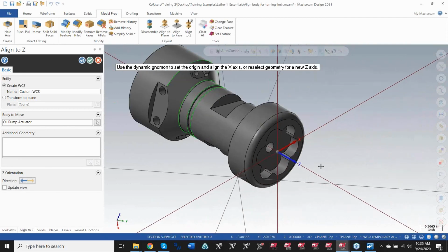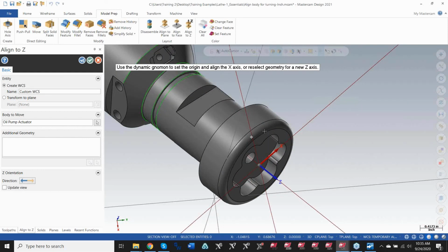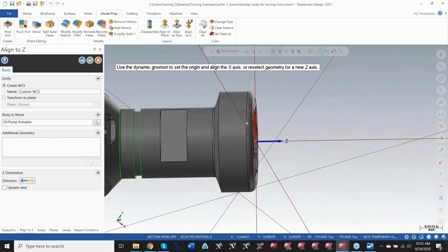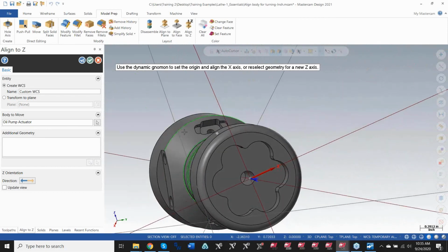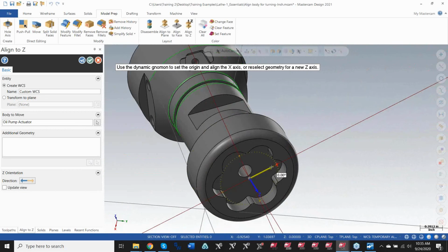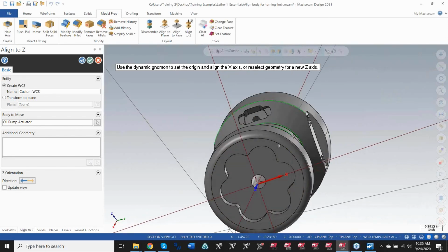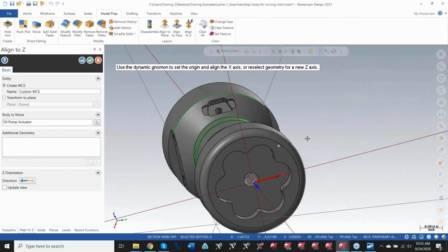and you'll see all these axes are all over the place, but the one you want to pay attention to is this Z and the X, right? So right now, as it stands, if I'm looking from a top view, there's going to be my Z and my X. Now, if this flat would be at that angle, particularly when I finish it, maybe I want to rotate that X right here, just so that way everything's aligned properly to that flat. So maybe I want to rotate it, I'll find myself a quadrant that exists in here somewhere. If it's there, right there. So shifting that a little bit more is going to allow it to be a little bit more flat. Pretty sure that's all flat together.